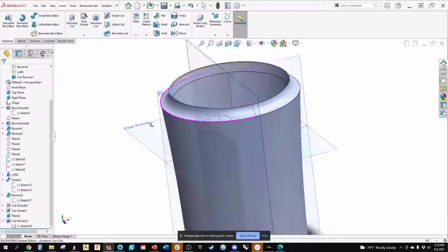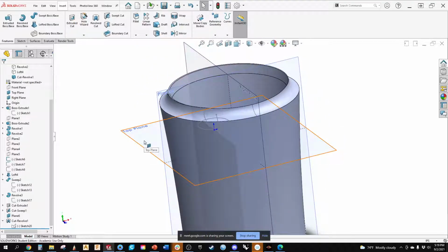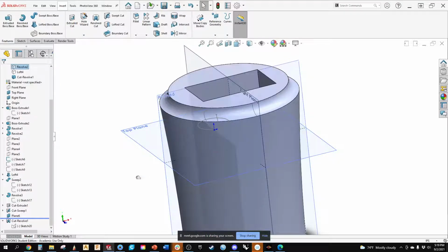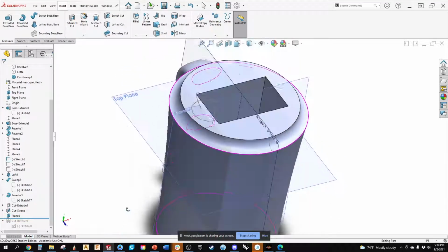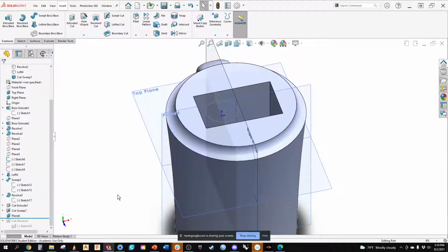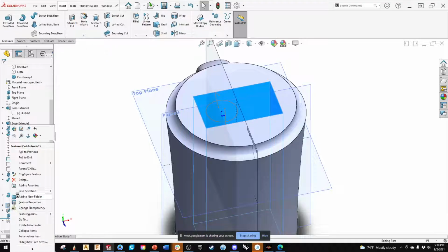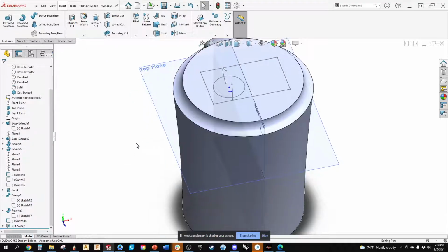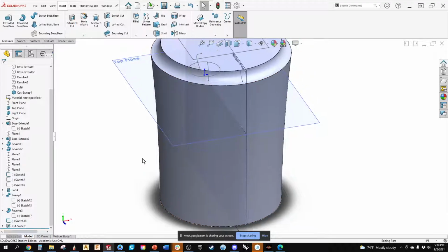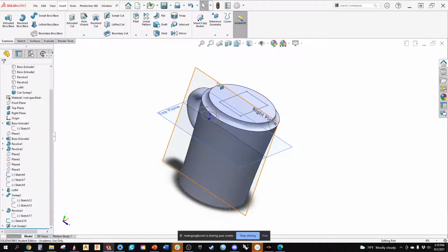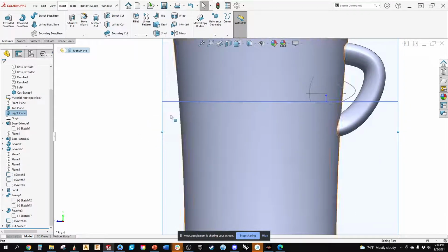And we've got our cutout. So there's our revolved cut. And we can do that in a variety of ways to make scallops, different things. I know that you guys are working on a water bottle for one of the classes, right? So let's say this was the water bottle and it had that scallop out in the middle. Let me come back. I'm going to delete this cut. So let's say I wanted to put a little scallop in the side of here. What I can do is go to the right view. And I'm going to do a sketch.